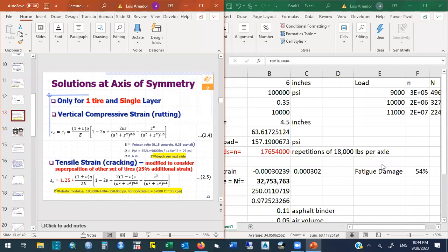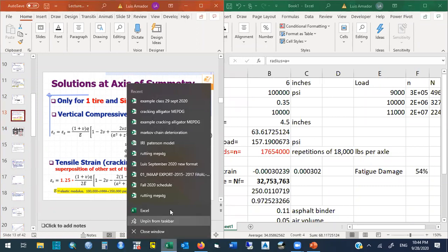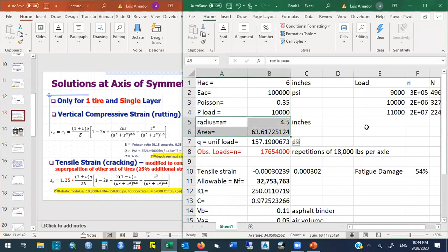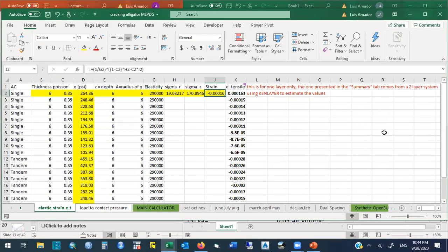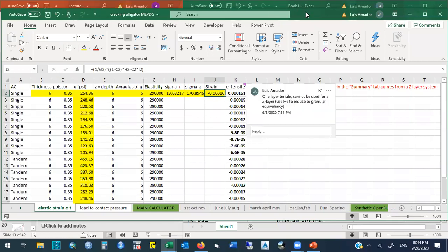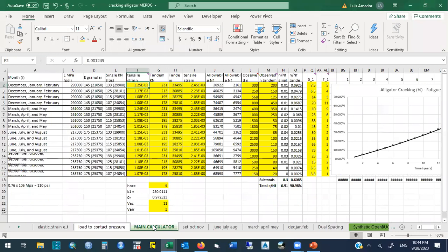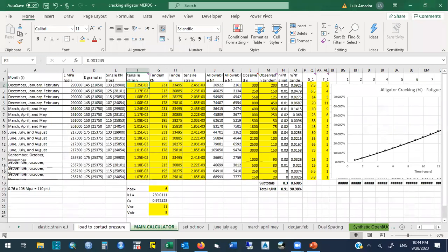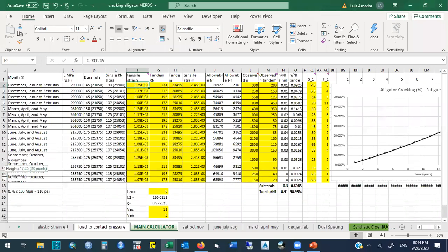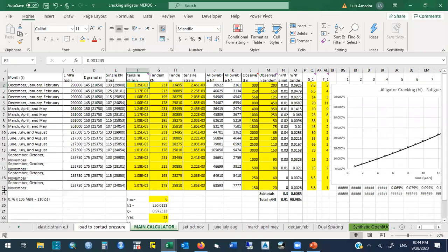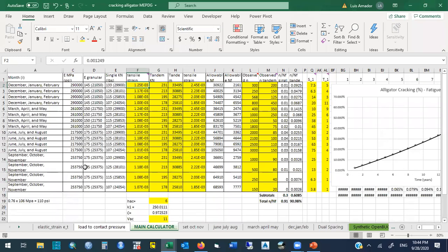That is difficult to estimate, it takes time. So in this example, you are basically just changing the loading, the axle load. So, in reality, are we just taking basically the worst case axle loading if we are calculating fatigue damage for a particular pavement, whatever weather conditions? This is a little more realistic, but this takes like one day of work to estimate.